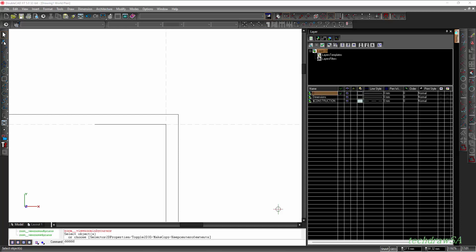And let's say you want to now place a JoJo tank or something here on the outside at a very specific distance or whatever. So what you will first need to do is go and draw a construction line that is aligned with the wall's outer edge. And then you will obviously measure out the distance that you want the JoJo to be. Let's say you want the JoJo to be a certain distance, like say over there. And you have specific measurements.